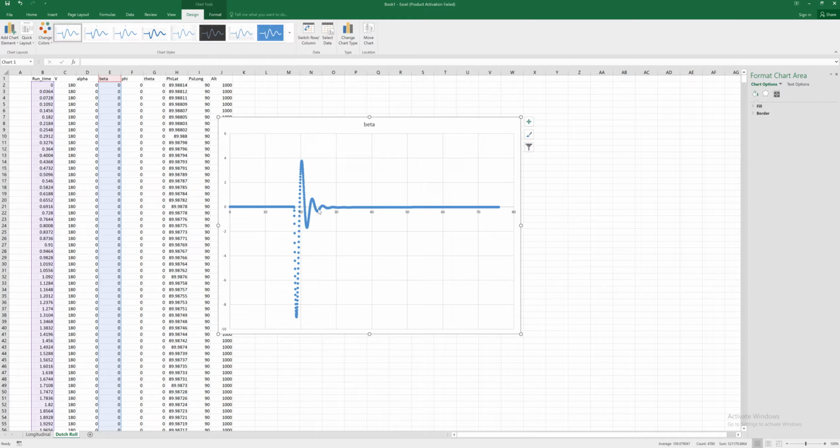So this is our side slip angle, and you can see from that rudder kick we had this kind of high frequency response of the aircraft. That's the Dutch roll, and again we can see that that's convergent. The peaks are getting smaller as time goes on. Again, this was a step change, right about this time point here, and so we could zoom in on this